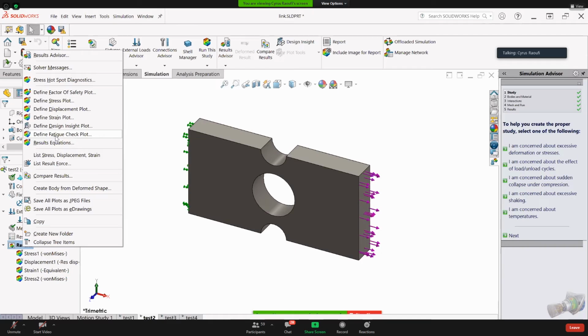If you don't take care of fatigue and don't realize that, and you design for yield strength, then you think your factor of safety is, say, 5, but the reality is the factor of safety is 0.5, because you didn't consider fatigue. All the equations for factor of safety are there, but it's not working because you have fatigue. Now, how should we know that fatigue is a concern? That check plot is going to help us.